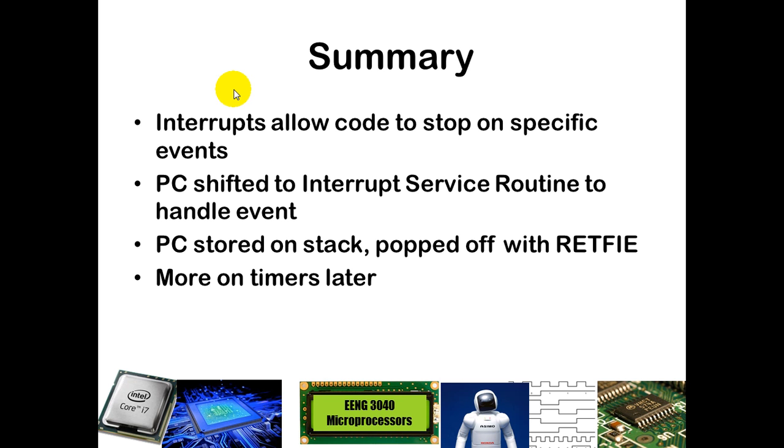And when you finish with the interrupt, you should restore the values that you may have stored, the W register and the other ports and any variable values that may get modified within the interrupt, and then you should have an RETFIE. And we'll talk more about timers in the next lecture.